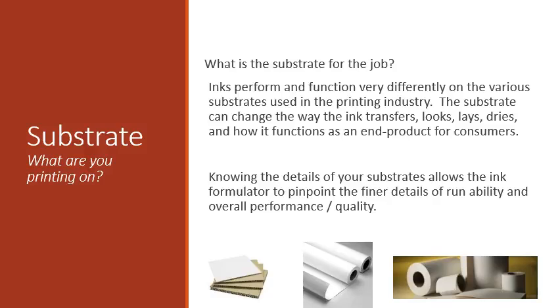By knowing the details of this substrate in conjunction with volumes and what the job is, the ink formulation can formulate around creating the best lay possible, the best color consistency, the best pop in color, the best rub resistance, the best runnability, so you can achieve the highest speeds possible once we've interconnected the substrate you're running on to the volumes you're laying down to ultimately the job we want to create. So that's the third piece.